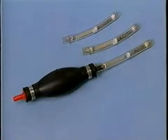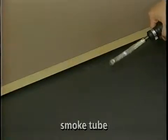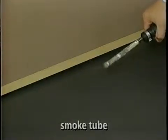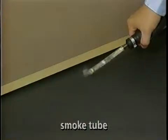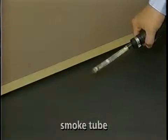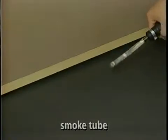You can buy smoke tubes such as these from safety supply companies. Slowly release the smoke in the hallway at a point about 2 inches out from the center of the door. Aim the smoke in a direction parallel to the room door. If the room is at negative pressure, the smoke will be seen to go under the door and into the room.